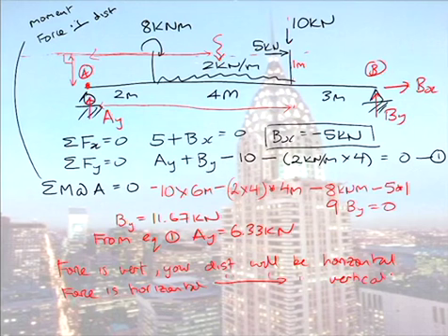So with respect to the test paper you sat the other week, in the first question, there were horizontal and vertical forces. Where people got them wrong was they forgot to take into account the moment caused by the horizontal component. Okay? So horizontal forces can cause moments.